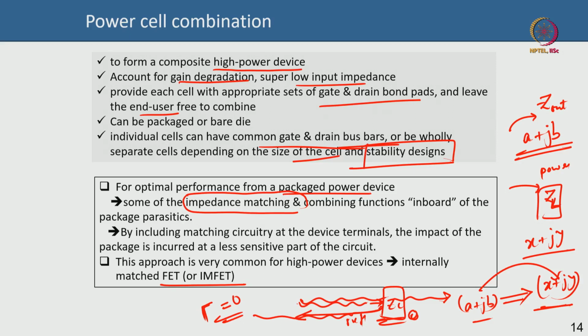As the frequency increases you cannot use a lumped element. You can buy these resistors from the market, from the street shop. You can buy resistors, you can buy capacitors, you can put them on a board or a PCB that works for lower frequency, maybe a couple of gigahertz. But when you go to higher frequencies, X band, K band, Q band, etc., those kind of approaches are very difficult because your wavelength of the signal, lambda, is actually very low, you are approaching millimeter wave.